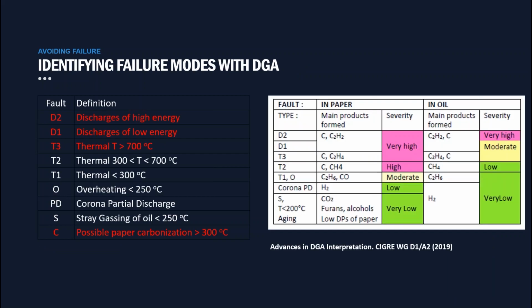Let's look at dissolved gas analysis in slightly more detail. So this test, DGA, has been used to monitor transformer condition since the late 1960s. From your 50 ml glass syringe, we try and identify these faults on the left. It's important to note that more than one fault can occur at any one time, and so this complicates the analysis and also the condition assessment.